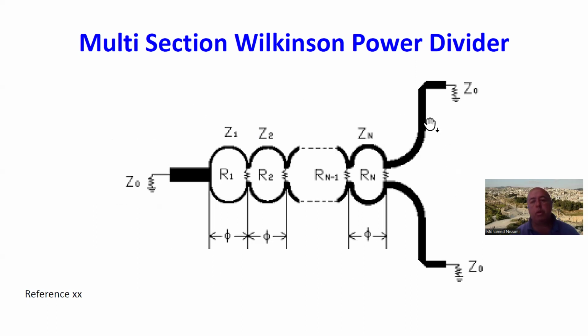So what I'm going to do today is 2 examples based on this. I'm going to do one from 2 to 6 gigahertz and another one from 2 to 18 gigahertz and show you some of the challenges in these designs. They're not trivial. The theoretical design work is easy, simply done by table lookups or computer-aided design apps. But when you go to the implementation and model it, you realize it gets much more difficult, especially if you're talking about frequencies above, say, C-band, above 6 gigahertz or so.